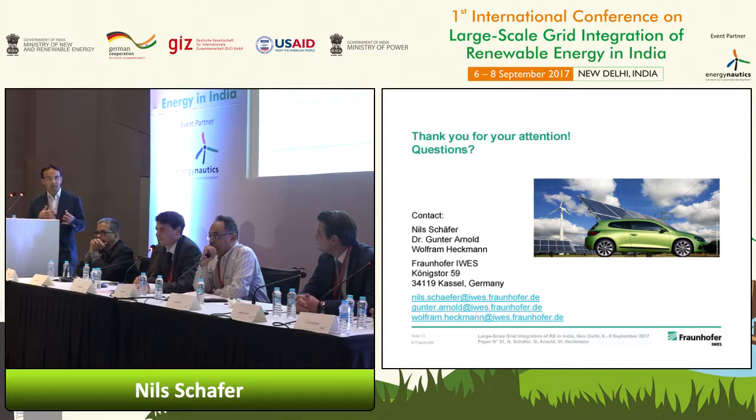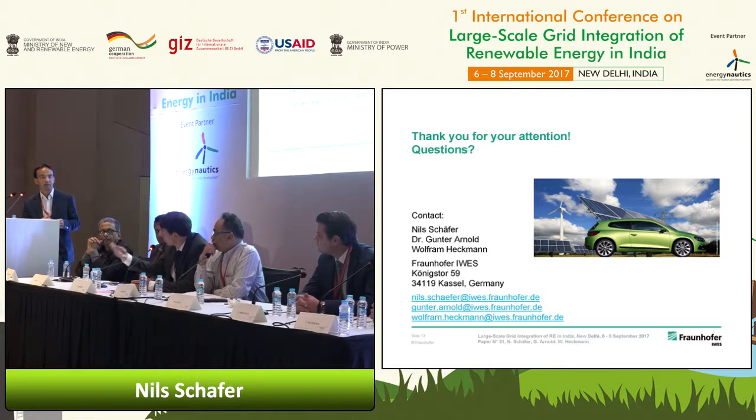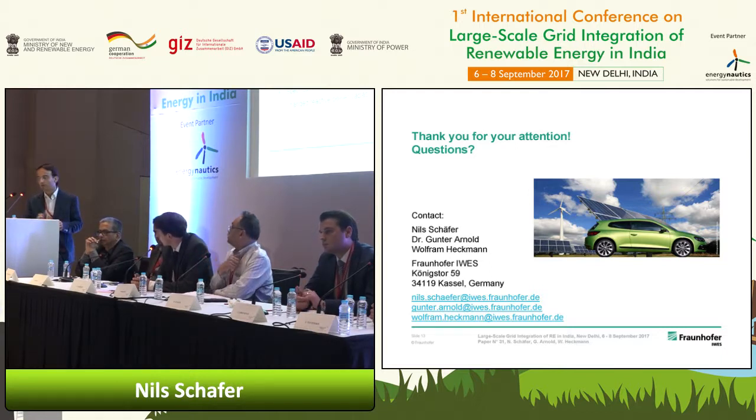So it's a ratio of the rated power of the connected equipment in ratio to the connection point. Like a minimum required short circuit power, in relation to the power plant you want to connect, basically. So this is how I understood.